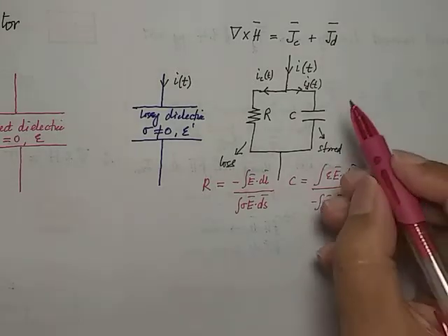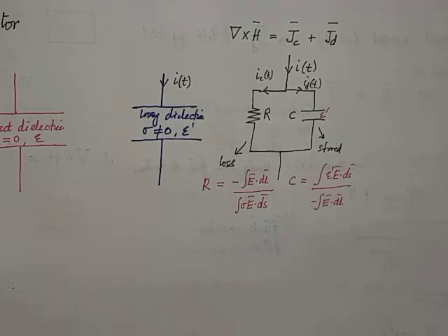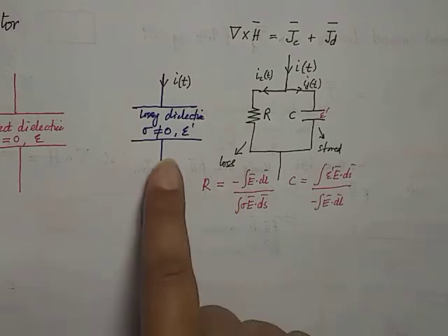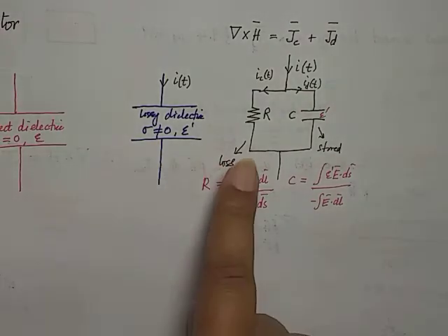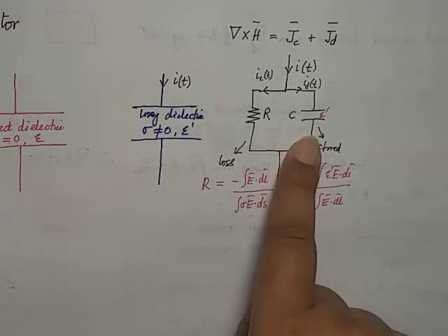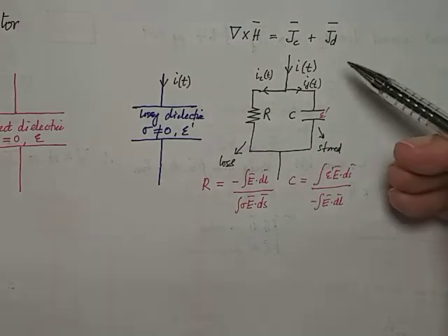The material here should be epsilon prime, remember? So that should be the equivalent circuit of a lossy dielectric, because in the final exam, I presume this is going to be a popular question that has always been asked before. When you use a lossy dielectric in a capacitor, we produce two components, and we develop these components based on the Maxwell equation we developed earlier.